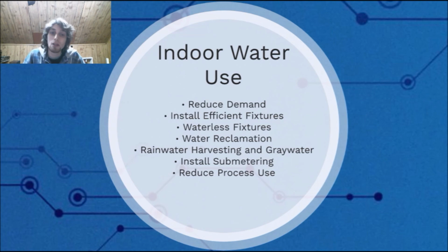Use high efficiency or no flush fixtures at all. Use gray water reclamation systems. Install efficient fixtures. Now, high-performance flush and flow with a WaterSense label, they could be 20% more efficient, and they're brought forth by the EPA to help consumers save water. So if you use these systems with a WaterSense label, you're probably on target to meet your 20% of reductions.